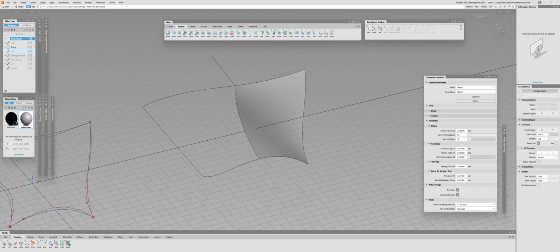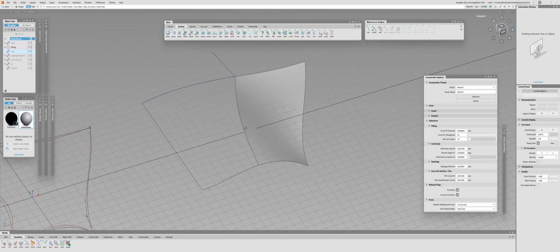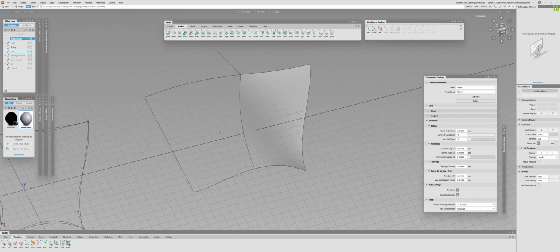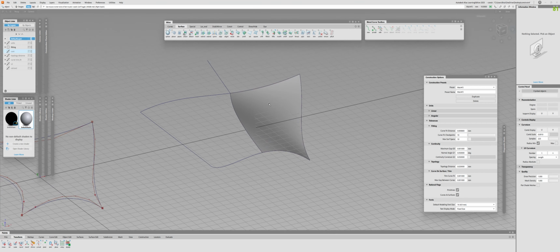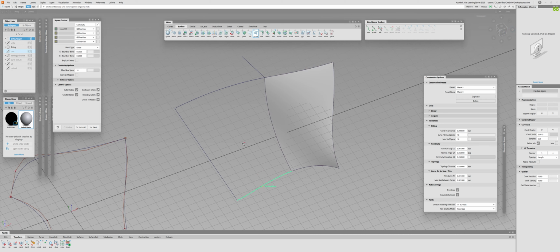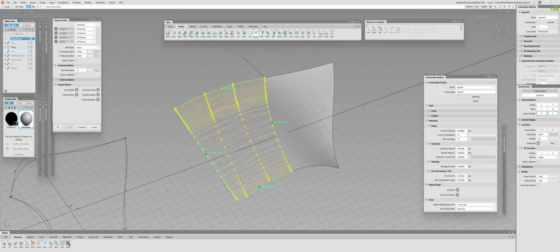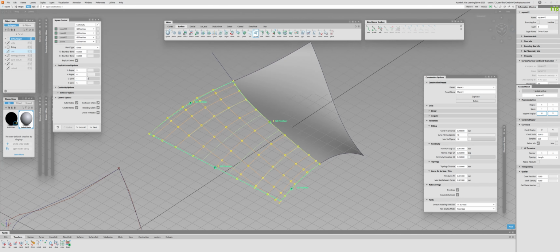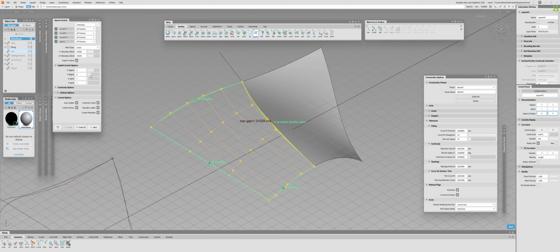Now, how many samples Alias will take to calculate the accuracy. It's heavily used for the surface continuity tool. Let me show it to you as an example. I will create another square tool. I'll click on explicit controls, and I would like it to be positional, so let me try 5 degrees.